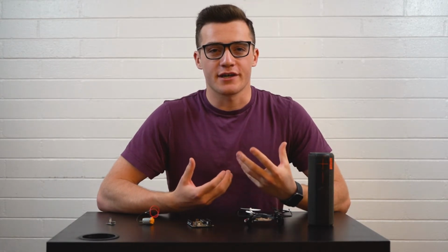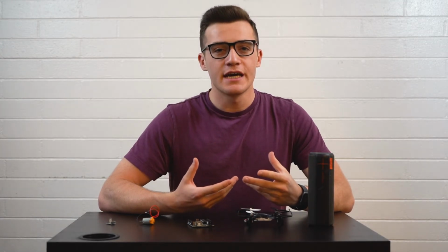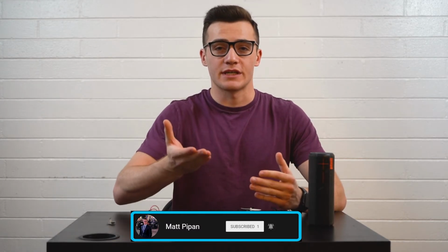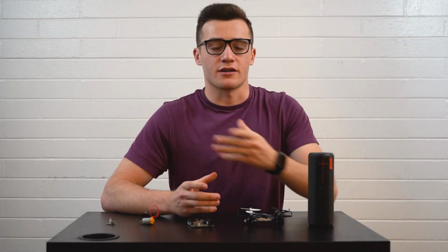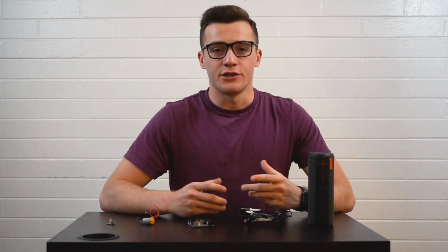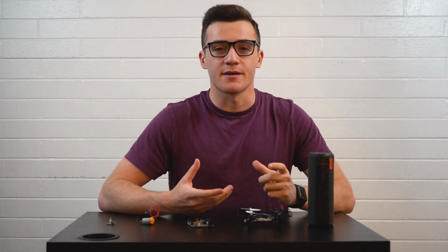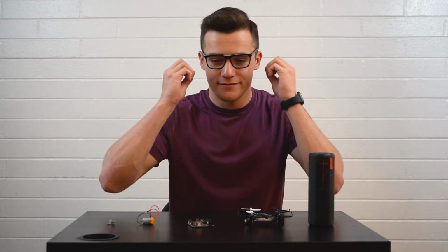And this is a revolutionary concept because it allows us much more precise control over all sorts of devices. So we can do things easily like finally controlling the speed of a motor, or we could change how audio signals sound, or like you saw, we can even change the brightness of a light. We've gone and made our own digital to analog converter, or DAC for short, using just 1 bit or 1 piece of information, which are our high or low states, and that allows us to get any value in between those high and low states to mimic an analog signal, but by only using digital values.